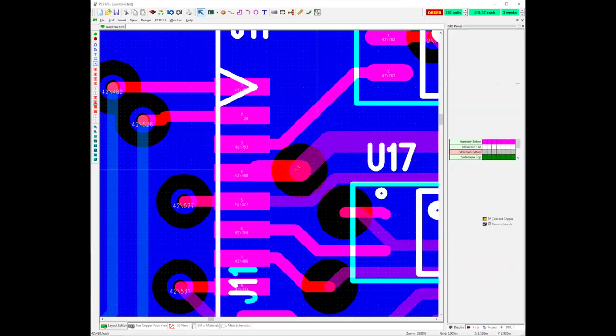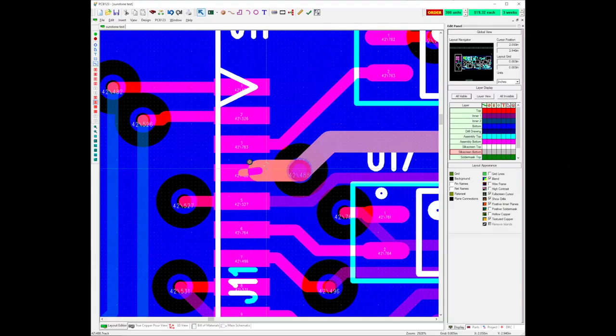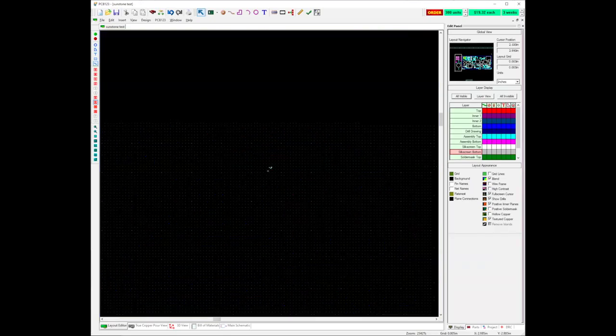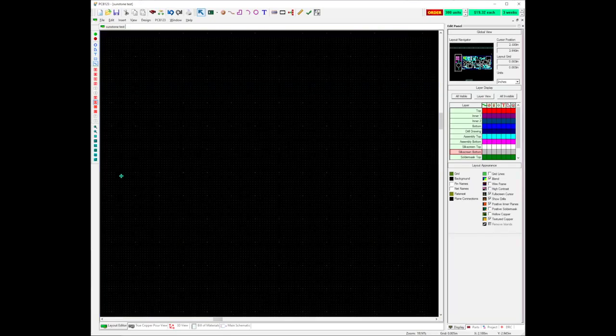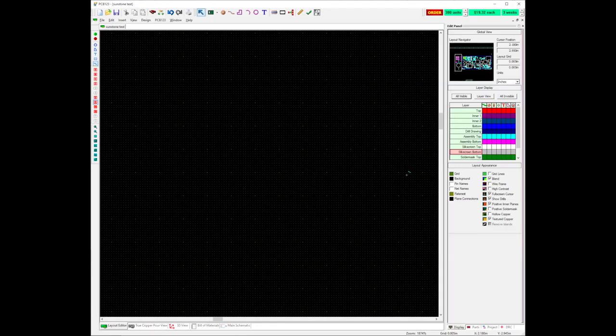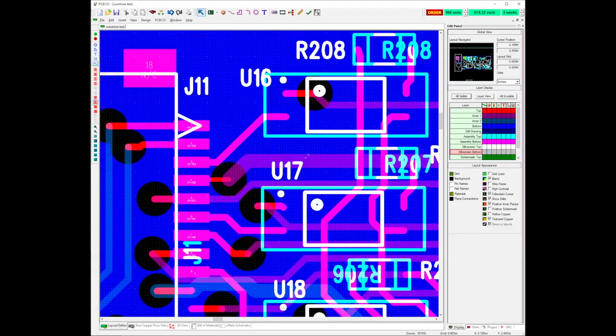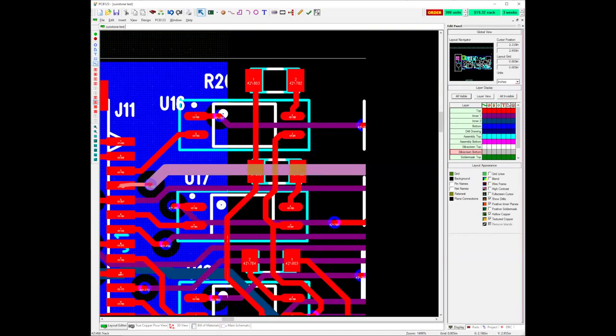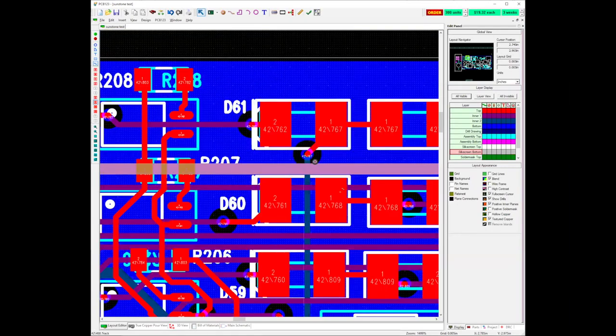10 thousandths, and it still leaves an error because I've got an extra vertex here. So change that one. That fixes all those errors, but I still have to go back and find this other error that I created for myself and fix it. I've got a via here that's too close, and the easiest way to fix that is just to drag it up a touch.